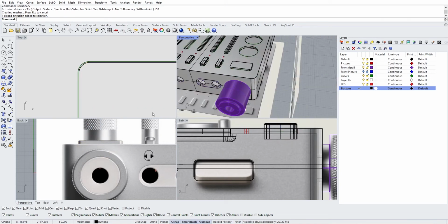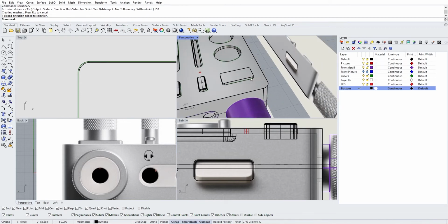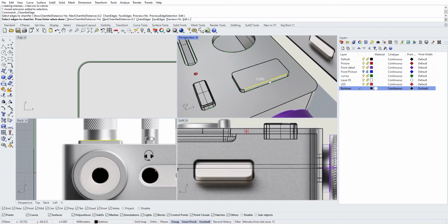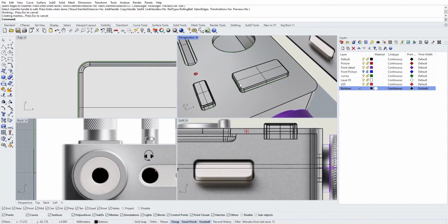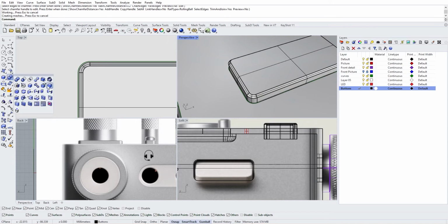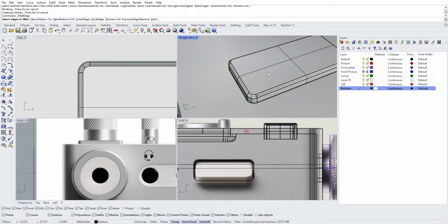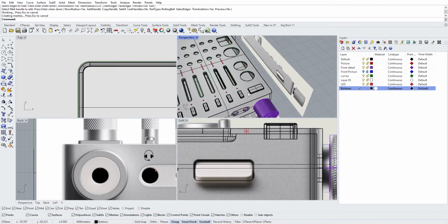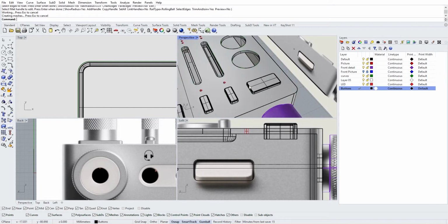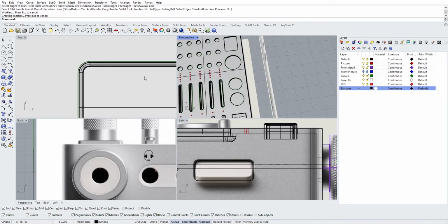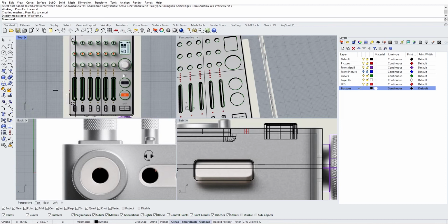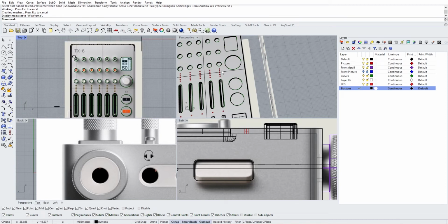put, let's look at the detail of how is this. So this has the same detail as those. So we're going to do a chamfer followed by a fillet. So 0.2, enter, and then a fillet here of 0.05, like this. And then we'll do the two buttons which are here also. So let's check. Yeah, two buttons here, the screen, and here a knob.